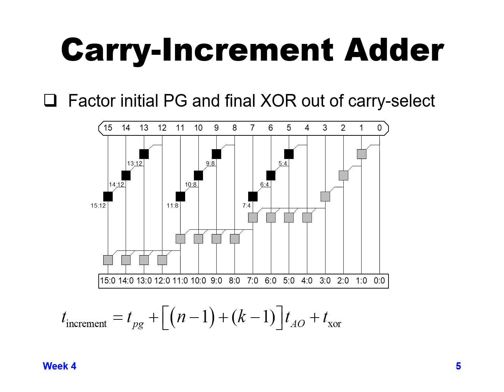And the actual function for this is we have our time to propagate through the P and G, propagate and generate values at the beginning, and then we have a T XOR at the end for the last bit calculating the sum, and then the delay through the middle bits is n-1 plus k-1.